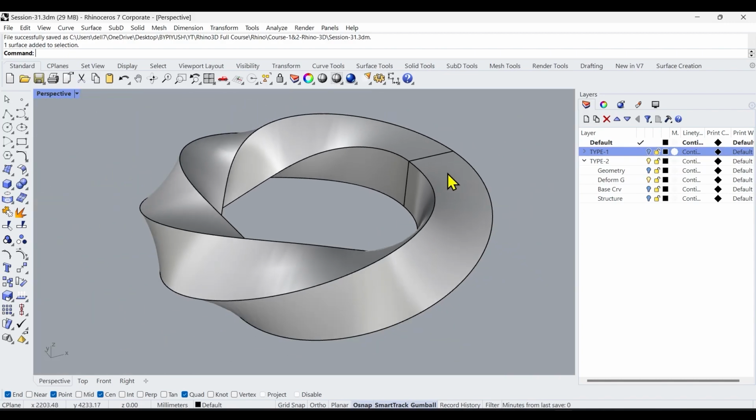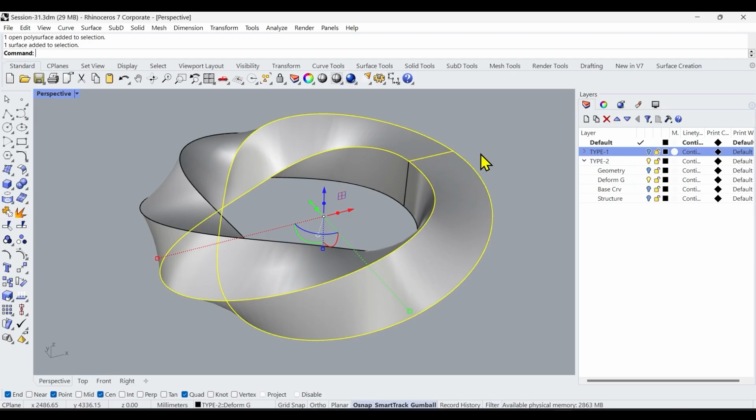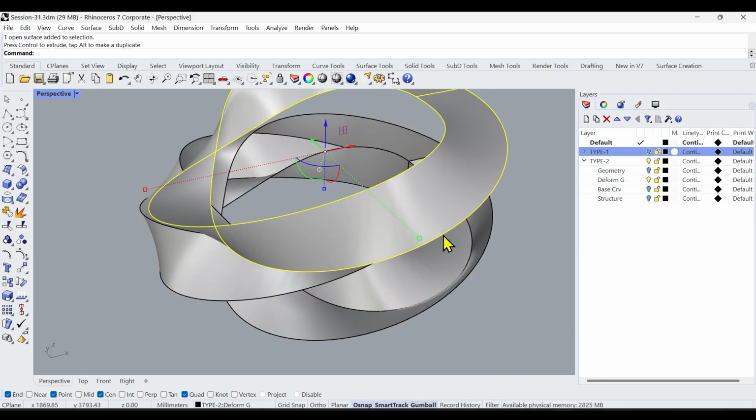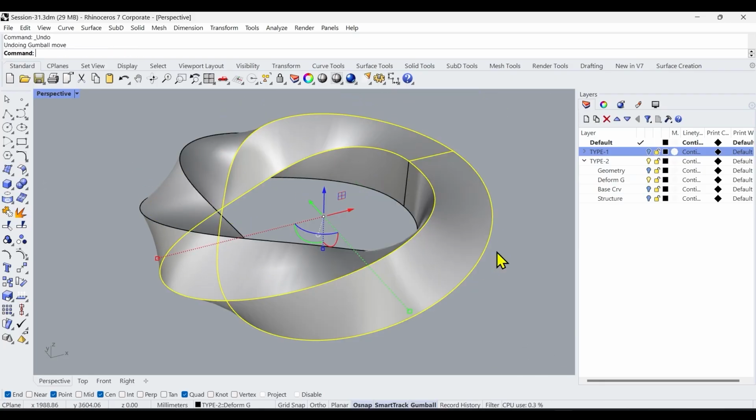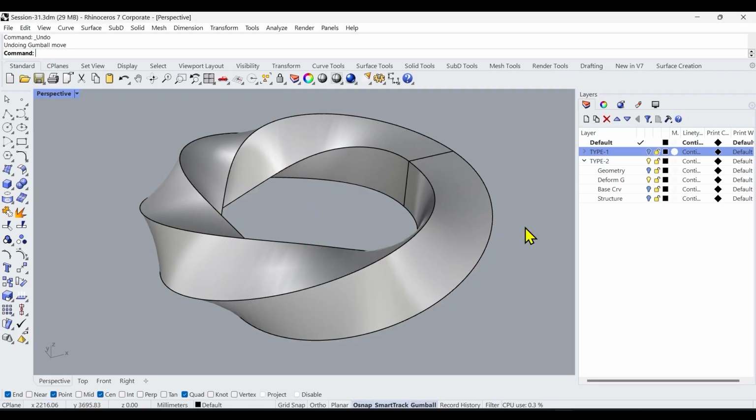Okay, so this is a whole thing. Either you can explode this or you can use Control Shift to select surfaces separately, and now you can right click to extract the surface. Right now, if you select, it is extracted and removed from that. It's not copied. So let's say I want it like this only.